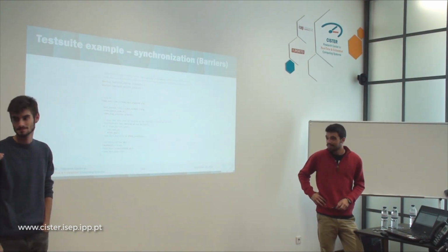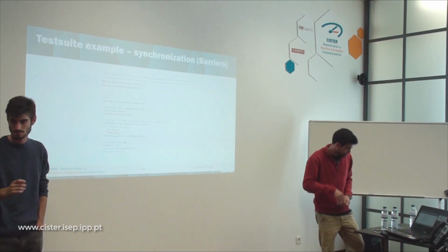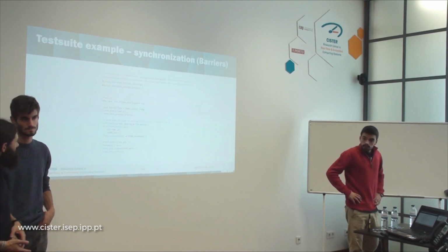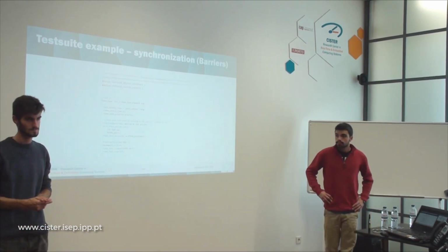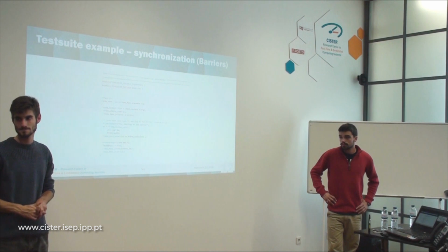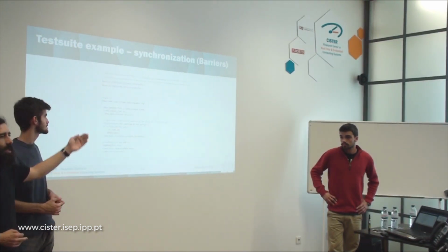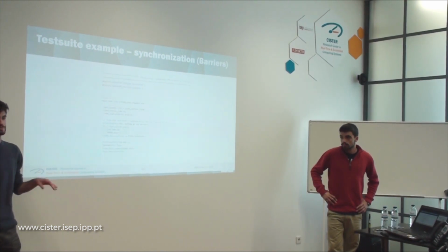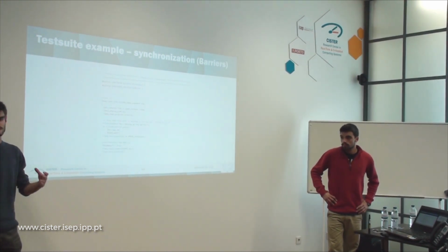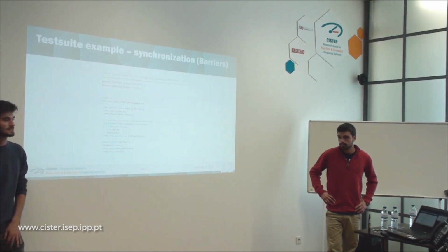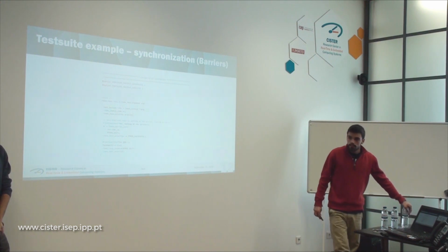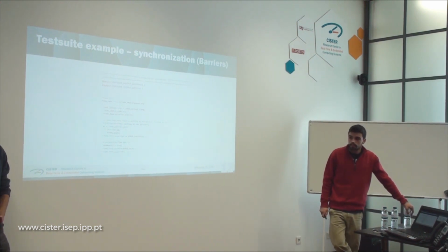I think it's because you need to know offline what you are dealing with. So basically you are specifying exactly how many semaphores you want, how many barriers you want. For example, when using message queues, you also have to specify the memory that you're going to use for each message. I think it's because you want it deterministic, and you want to make it deterministic at compilation time, so that's why they make you use this kind of configuration.